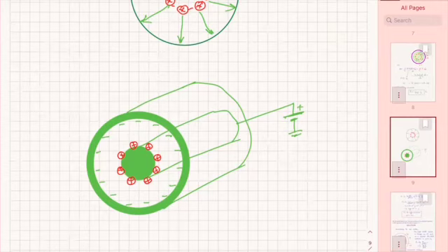So what happens to the outside of the external conductor? Yes, all of the positives will try to go here. But we are not going to allow them because we are smarter than this. We don't want these positives to be out because they're going to radiate. Could you believe it? Have a coaxial line to feed your TV and then this line to act as an antenna? That's why TVs sometimes don't work. They have all of this noise, you know. They have double images. They have all kinds of different things, usually noise, because your conductor probably is not well grounded. The first thing I would do is to check that one. So what do we do? We put a ground here. And when you put a ground, all of these disappear.